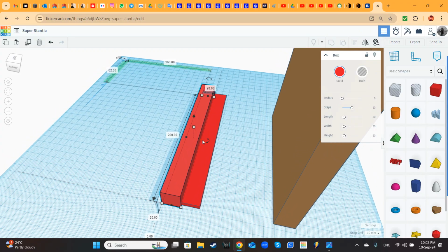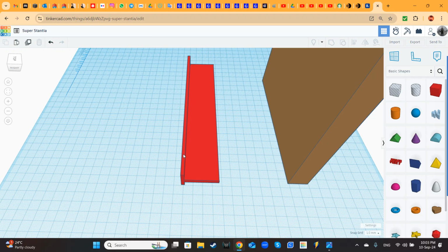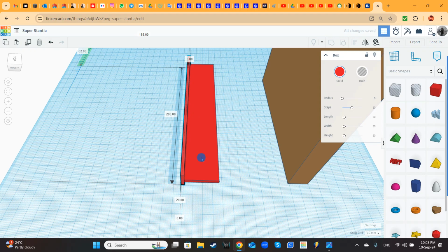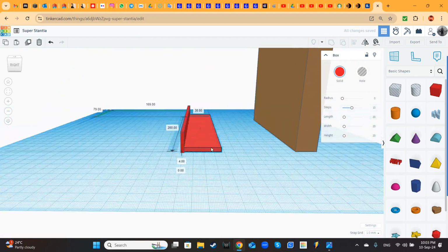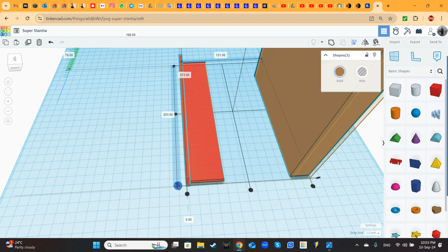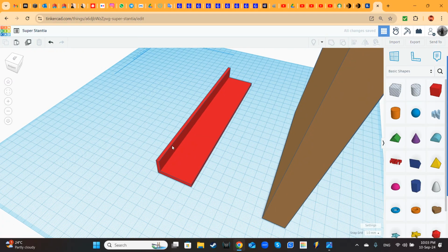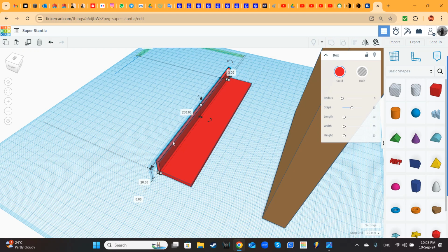And because this is just a wall, I am making it thin. Like how many millimeters? Let's see. 3 millimeters. That will do the trick. Okay, let me align a bit. I am using the align command. Okay, good. So, after having this wall, I am duplicating.